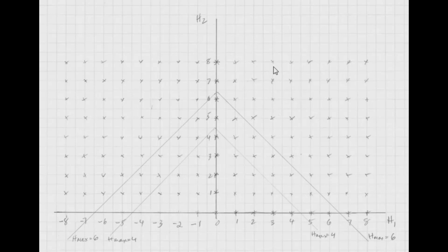Well, there's an option in Microwave Office in the harmonic balance setup where you can say limit the order of the products. So if you were to tell it, say, limit the order to 6, everything below this line would be included and nothing above that line. Or if you said to limit to 4, it would be this line here.